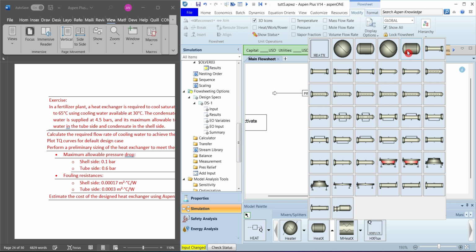Another common practice is, if the fluid is hot and everything else is acceptable, then put the hot fluid in the tube side. If we put the hot fluid in the shell side, at least there is room for the heat loss from the shell to the environment. So for that reason, we can put the hot fluid in the tubes. But on the contrary, it's also a recommendation to put cooling water in the tube side. So we have two recommendations in front of us. Then the choice lies up to us as of now for the preliminary exercise. So what should we choose?